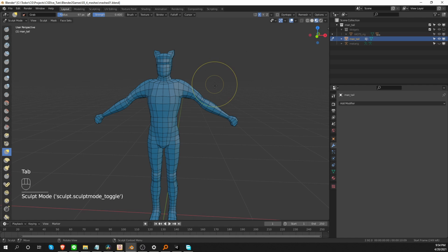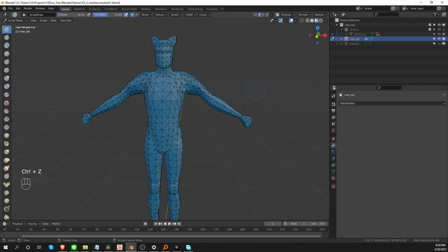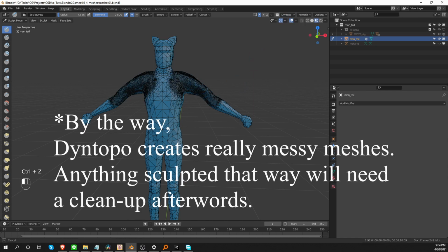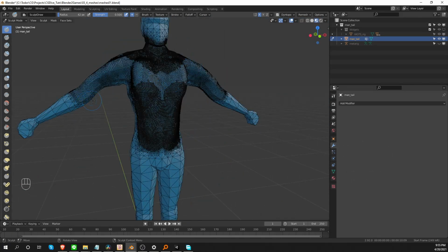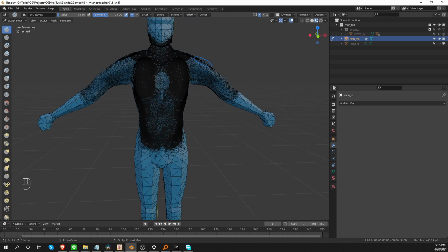but from time to time I see something like this. If I go to sculpt mode and enable Dyntopo and set the detail size to something very low and then start sculpting, you'll see that the polygons are getting really dense. And that is fine, for example, when you're concept sculpting, but when this mesh has to be used in a game engine or for animation or for something like that, then something needs to be done.